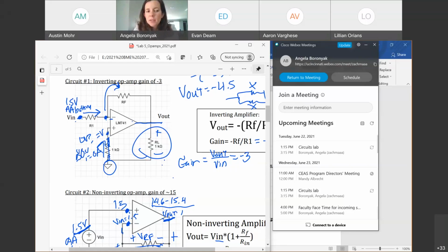If I have feedback paths, the voltage at one input has to be the same as the other. It's also 0 volts. So different than when I was here. Again, you've got to analyze each op amp circuit separately. They can have different hookups, right?